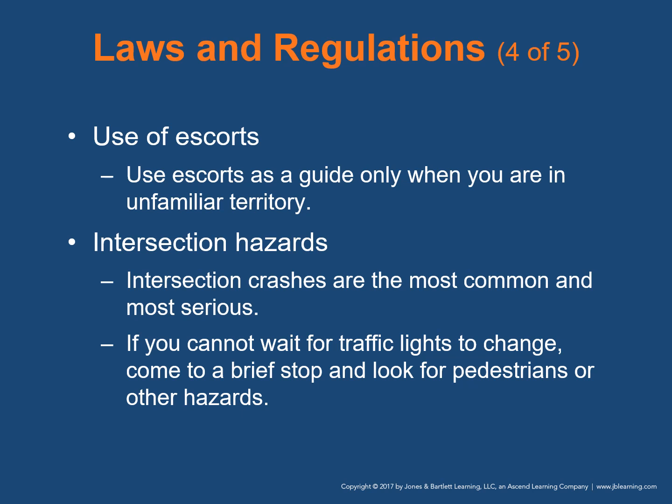Also be aware of intersection hazards. Intersection crashes are the most common and usually the most serious type of collision in which ambulances are involved. Always be alert and careful when approaching intersections. If you are on an urgent call and cannot wait for the traffic lights to change, come to a brief stop at the light and check for other motorists and pedestrians before proceeding.